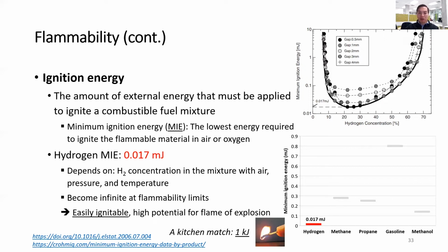And of course, if you compare to other fuels, for example, gasoline would be in the range of 0.8 millijoule, significantly higher than hydrogen. But even at 0.8 millijoule, a match of 1 kilojoule energy would already be able to ignite gasoline. So although hydrogen is really easily ignitable, with proper knowledge and proper handling, you would be able to handle it in a very safe manner.